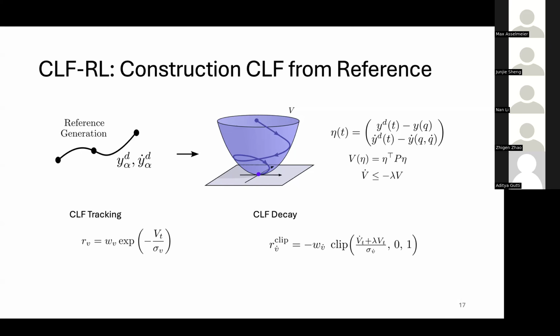I guess when you say position, it also includes the base position, right? That's the pelvis, our root frame of the robot. Yeah. And all of the values were relative to the stance foot position. This is because when we optimize a long horizon periodic gait, we didn't want one trajectory that goes out forever. So when you stance, all of your frame positions are relative to your new stance foot. I see. Okay. Thank you.